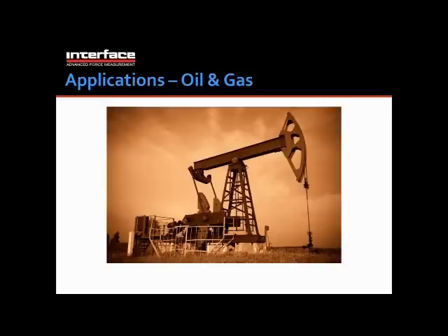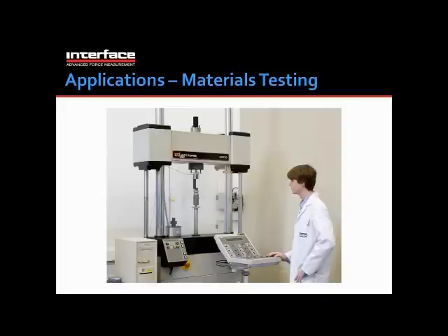Some other applications where you're going to find load cells: material testing. This is pretty self-explanatory. Load cells are the heart of these systems. The load cell is going to give the software on the machine the feedback to know exactly how hard the specimen is being pushed or pulled, and then also most likely give feedback to control that loading mechanism. So load cells are usually one of 2 measurements that are made on these machines, the other typically being a displacement measurement as part of the material test process.